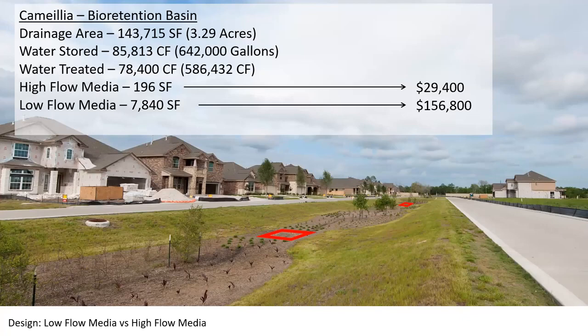So that's actually where the engineered soil system sits. And so that system's designed to drain at a certain rate, and that's how you achieve your surface volume. And we'll talk about this in the next webinar, this case study, but this is a really good example where you don't have to do your traditional design of a pond stuck in the back of the lot.